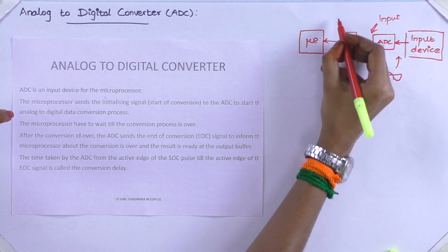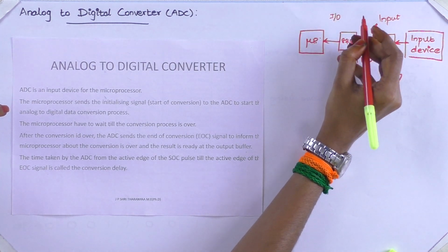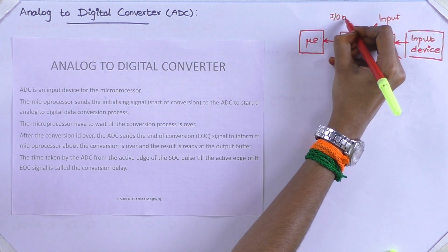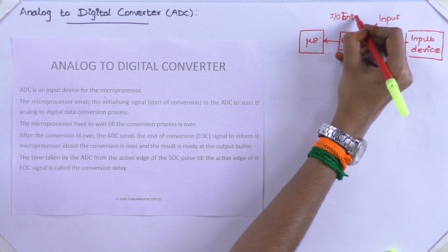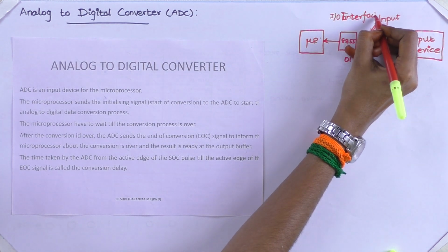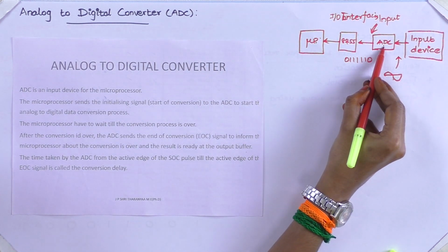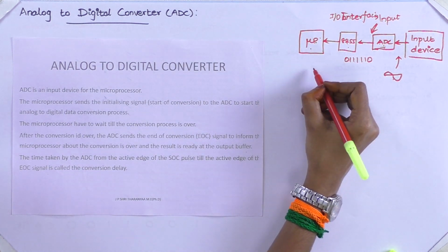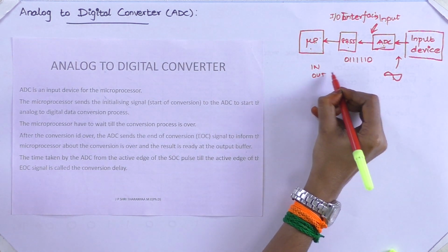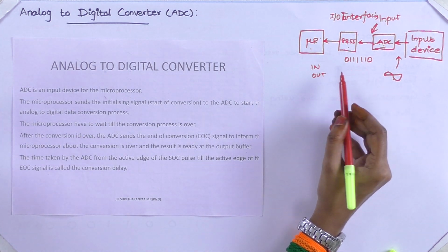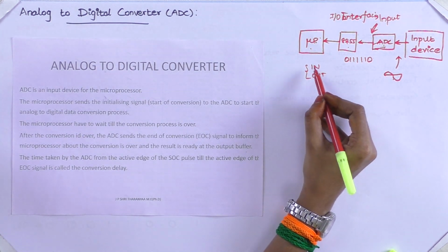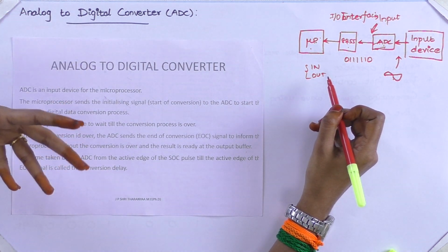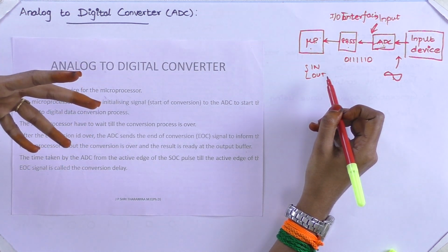So we are supposed to use IO configuration. IO configuration, in the sense we have seen in the first unit, IO interfacing logics. We are supposed to use that logic here for connecting the 8255 and analog to digital converter with the processor, and you are supposed to use IN and OUT instructions to communicate with this device. We will see later how to program, and what are the steps we can follow for this.